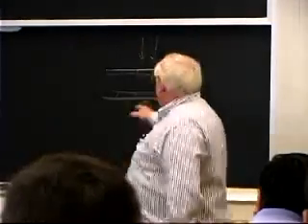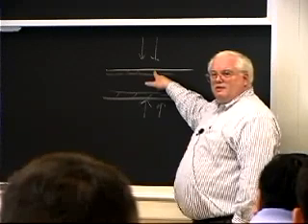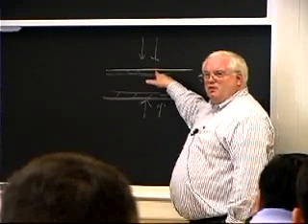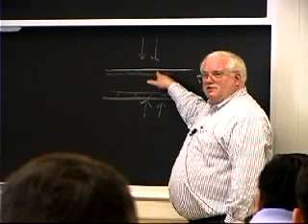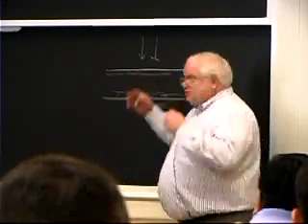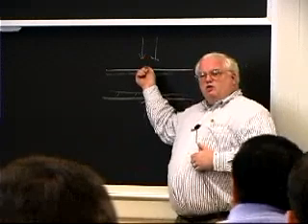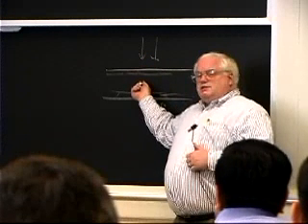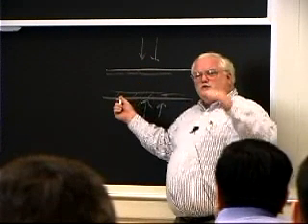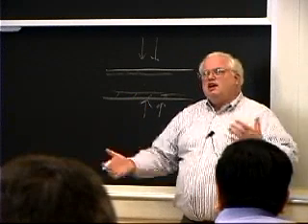If this cools more quickly on the surface, it shrinks. Well, initially while it's cooling, this is in tension because the outside's shrinking more than the inside, but it's all connected together, right? So this goes into tension when I cool it quickly, and the inside goes into compression. That's when it's hot. When it cools, it always reverses.